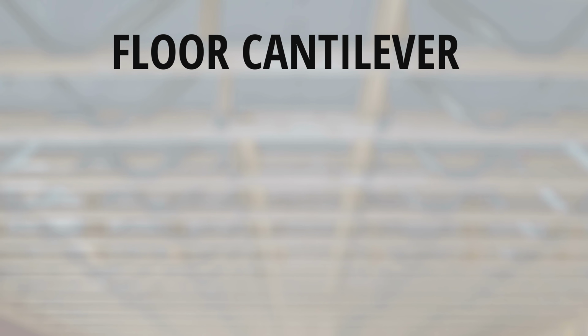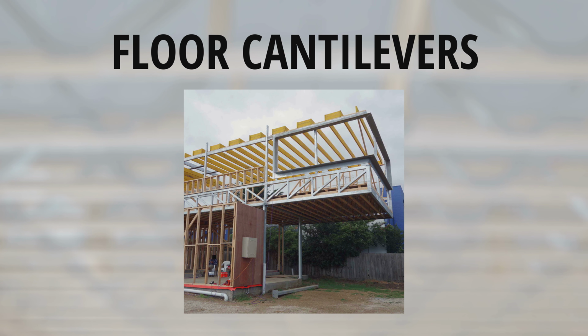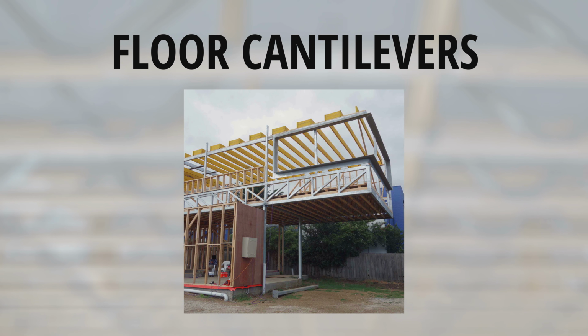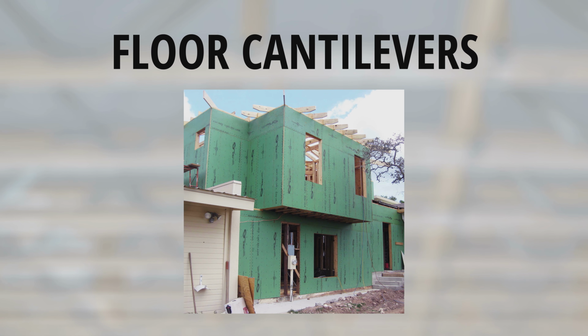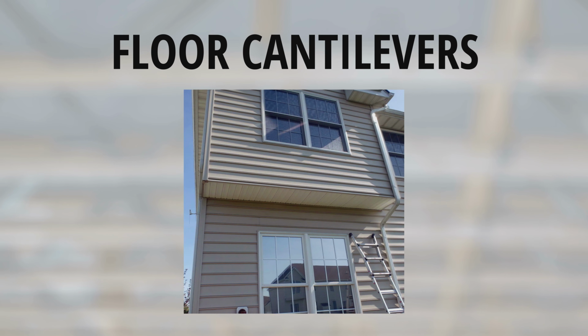Floor cantilevers. Double side joists for twice the distance of the cantilever. Rim blocking may be set 1 inch out from the sole plate to provide soffit nailing. Note: maximum cantilever equals the rated span of the joist system divided by 4. Cantilevers that carry significant roof loads or more than one floor load must be engineered.